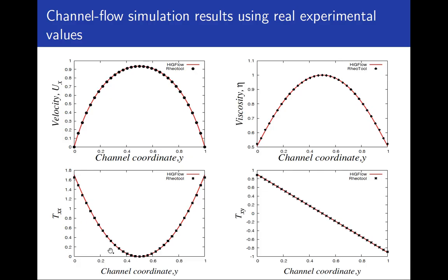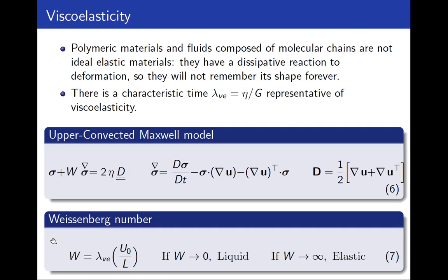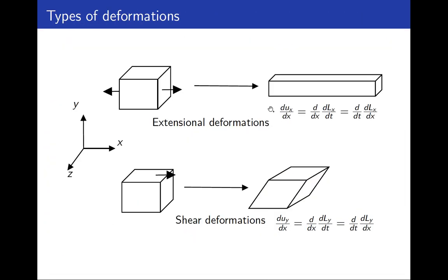For fluids like water, this quantity is going to be 0, but this fluid that I was studying was showing viscoelastic behavior. There was some level of elasticity in our fluid, so that's why we observe that this quantity is different than 0. So this quantity tells us to some degree the level of elasticity of our fluid. The higher this quantity is, the higher the extensional deformation.